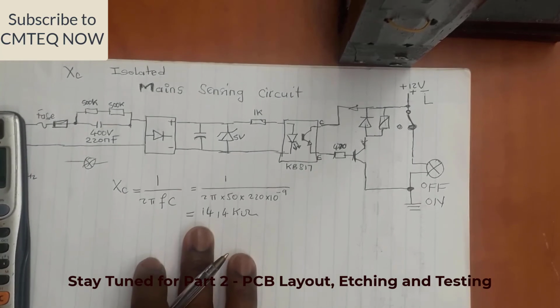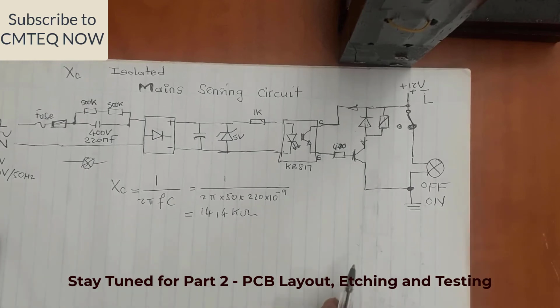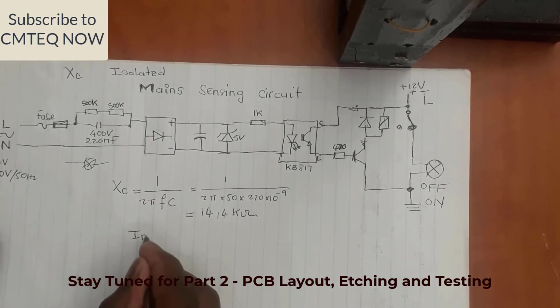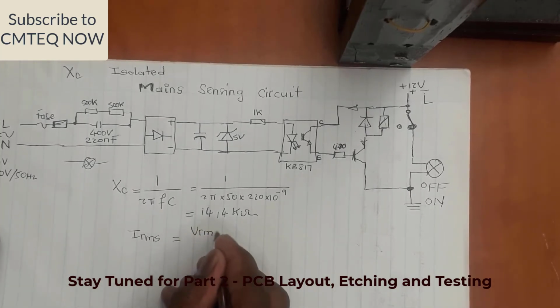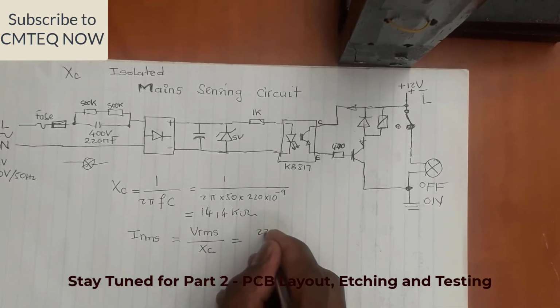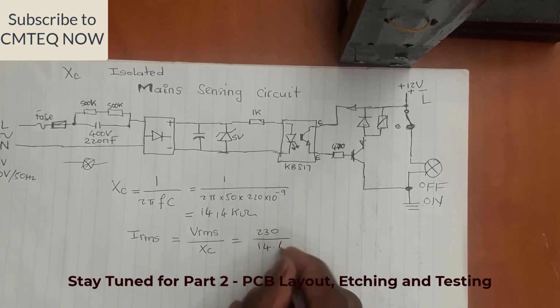So what will be the value of my current? The value of the current here will be just Ohm's law, so I RMS will be V RMS divided by XC. V RMS in the case of 230 volts will be 230 divided by 14.4 kilo ohm. Forgive me, my pen here is misbehaving.